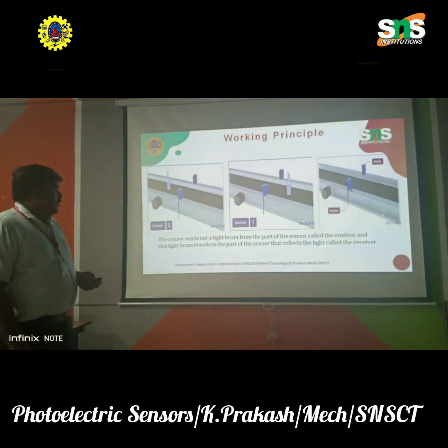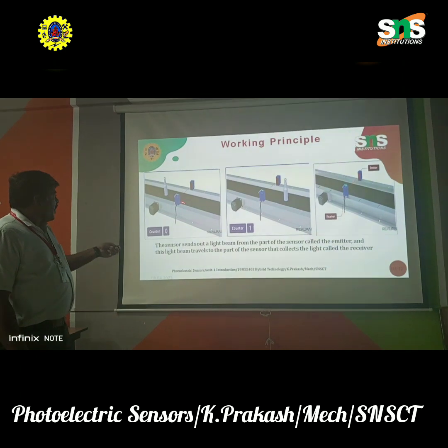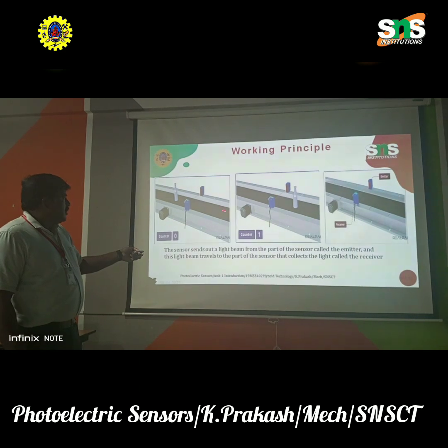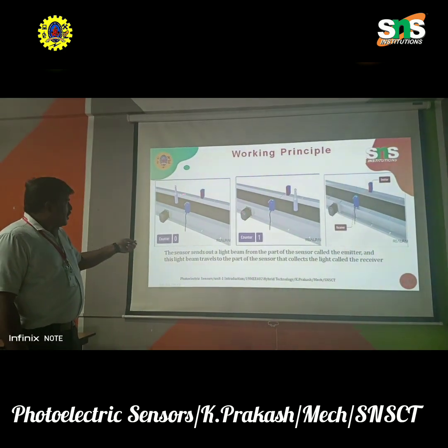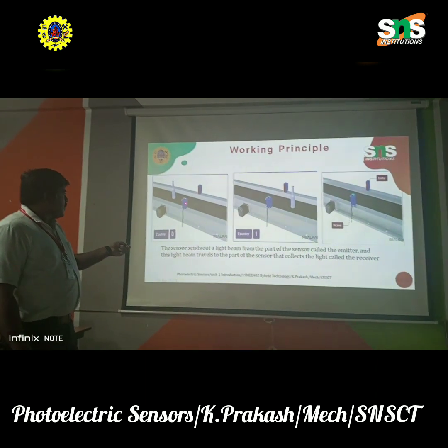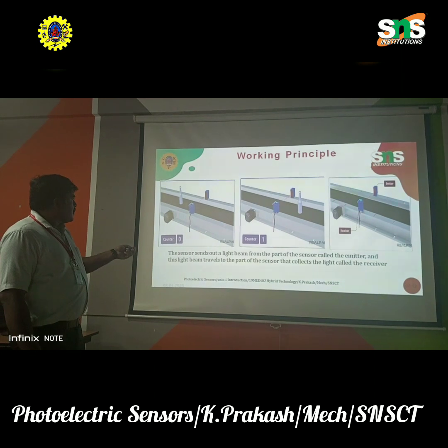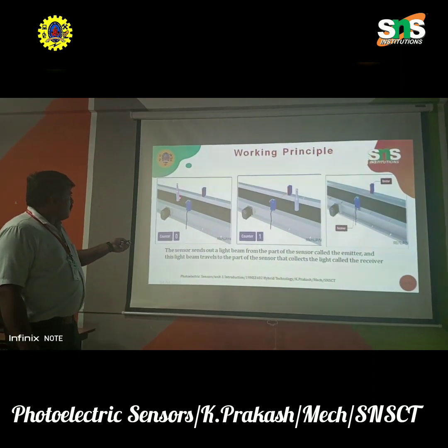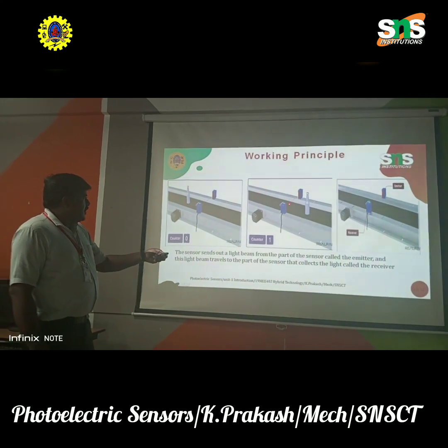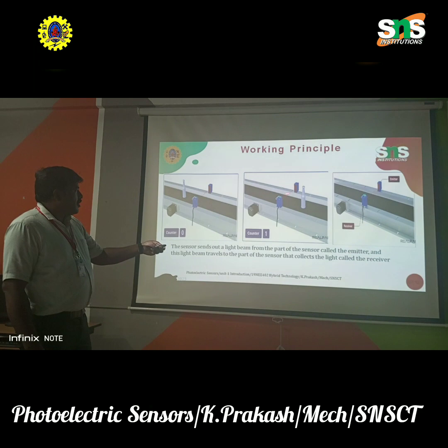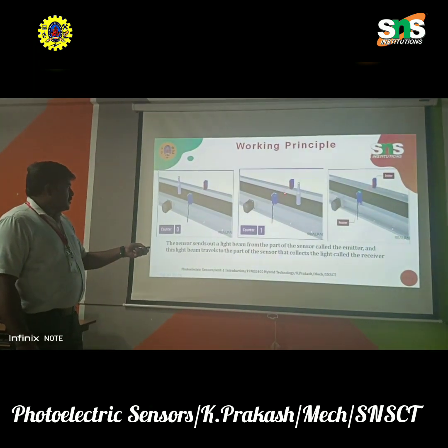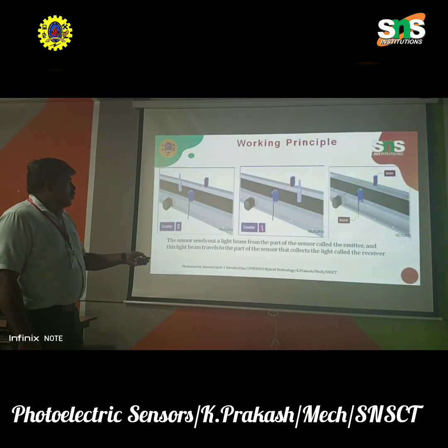Next, coming to the working principle. This is a process where the products come batch-wise in a production line through an automatic conveyor belt. Whenever a sensor is introduced here, the bottle will be passing through this sensor. When it passes, the light is blocked here. Okay, so the light source is obstructed, and automatically we get a count here.